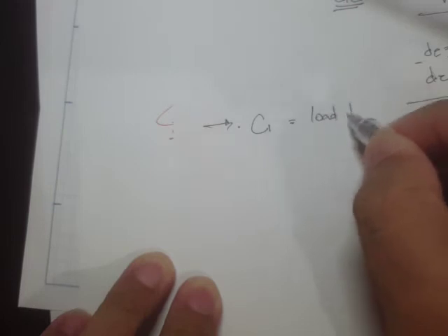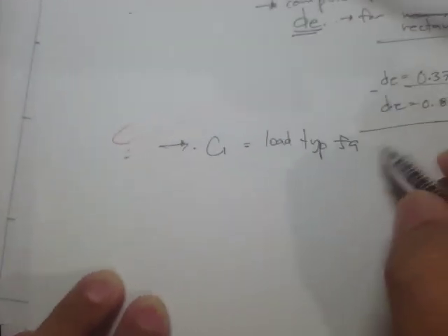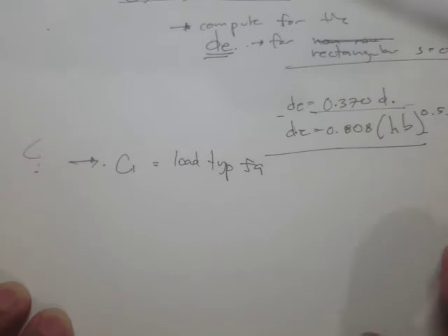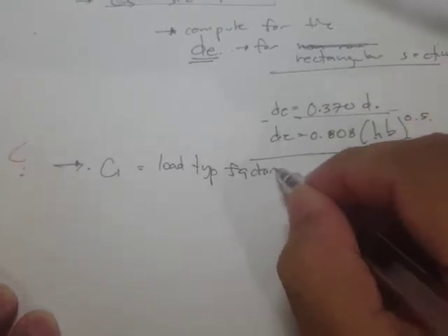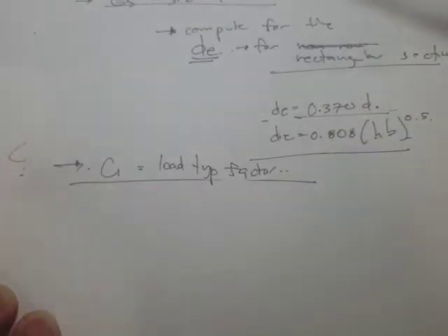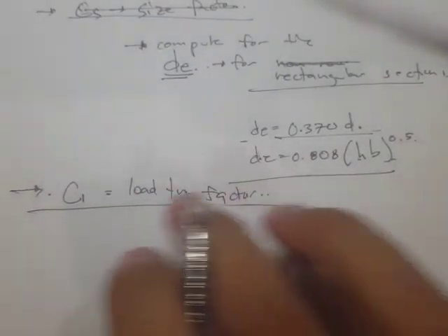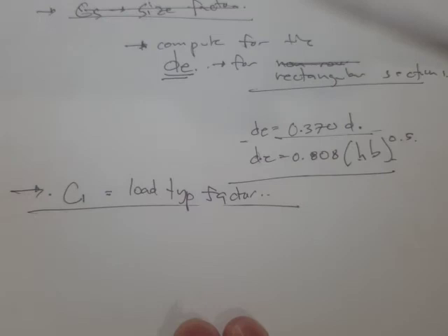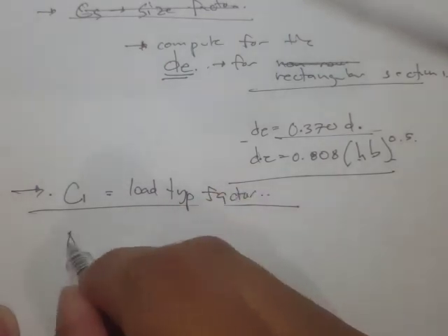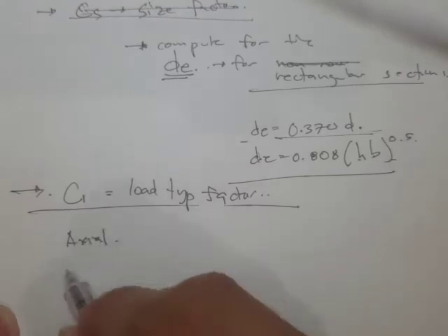Right, another one is the load factor. So, load type factor, C sub L. Okay, so the loading based on the standard test specimen is actually bending. Now what if our loading for our actual situation is axial, or let's say it's in pure tension.